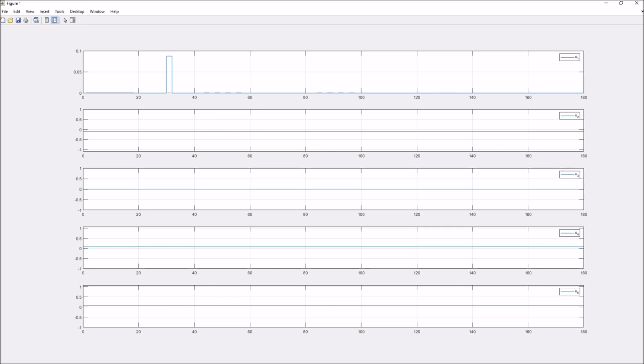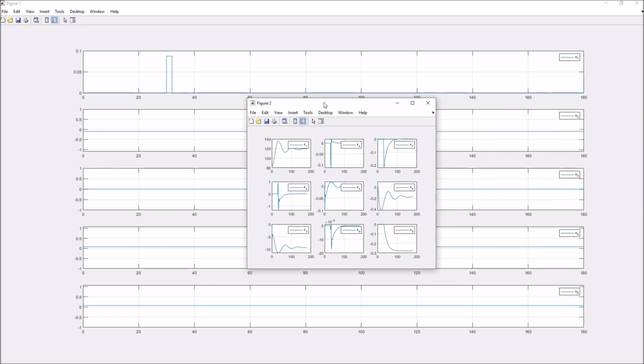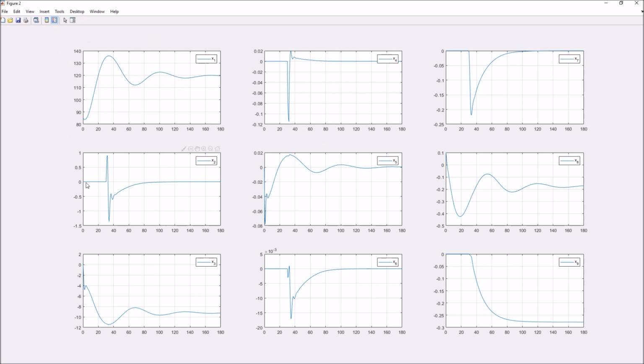Okay. Now what's interesting about this is, if you look at the state trace information, there's no lateral directional motion for 30 seconds, but then after you kick the aileron, look at this. You start inducing some sideways velocity. You start inducing a rate. That's exactly what the ailerons are supposed to do, right? They induce a roll rate. Therefore, it also induces a yaw rate, kind of as a secondary after effect.